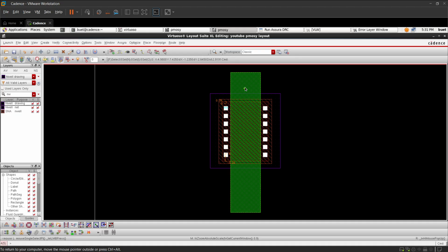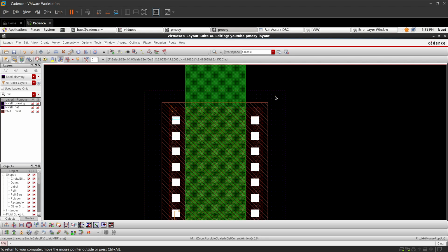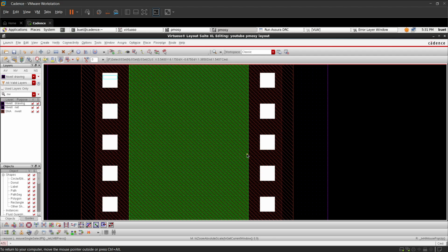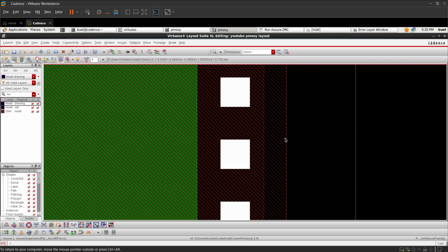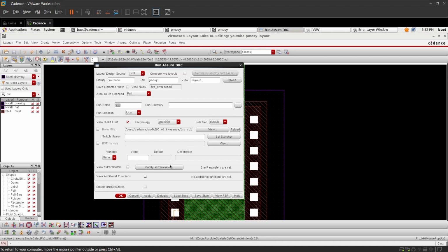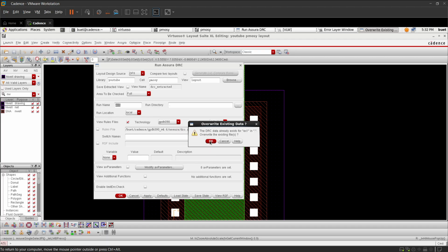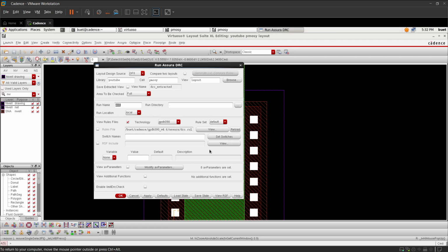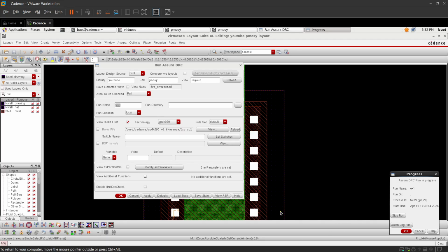It doesn't matter anyway, because for NMOS, just your drain and source terminal should be of N type. Done. Next thing, we are going to see what is the spacing between this P implant edge to our oxide. Check and save. Next thing, you are going to run the DRC again. So these are the steps you are supposed to follow while doing the accurate design.